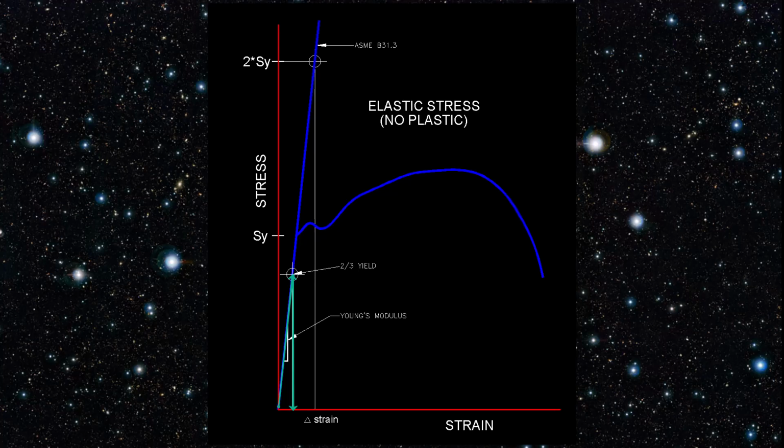If now the piping system were unloaded, then the stress would go back to zero, and we have now a cycle that can occur and is fully code compliant. This is the maximum strain/stress cycle that can occur for sustained stress. There are no thermal strains occurring for this cycle we have just seen.